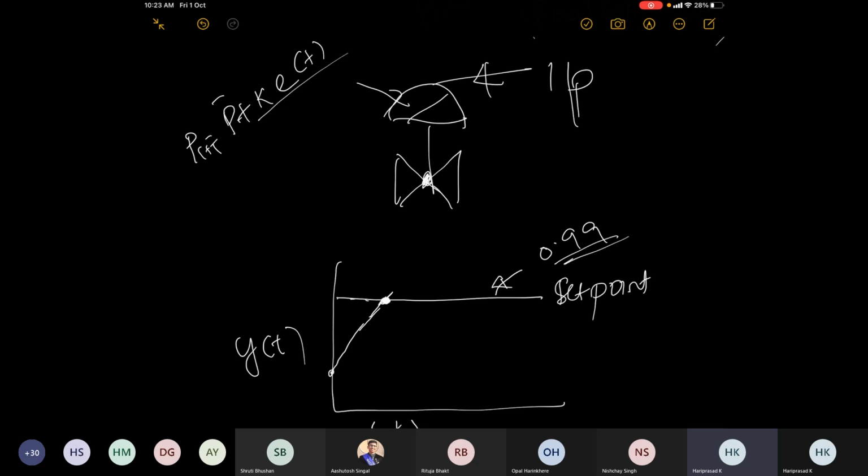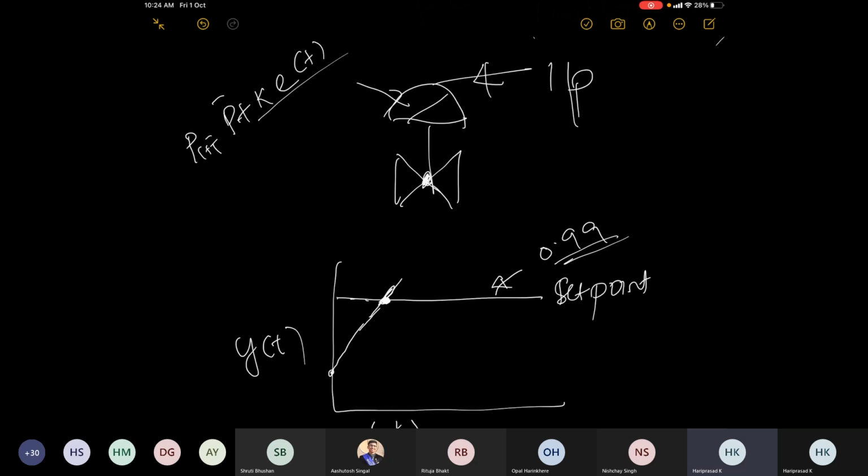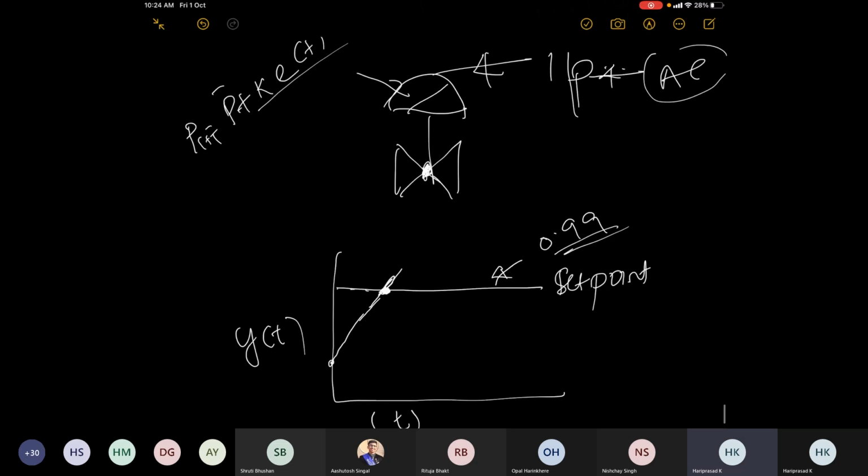But your dynamics is not ending here, right? So it might go up and down. Then again your control action would start. So when you look at the valve here, your controller is communicating to I to P, then I to P is communicating to your control valve. So every now and then your valve will get a shock whenever it crosses the set point.